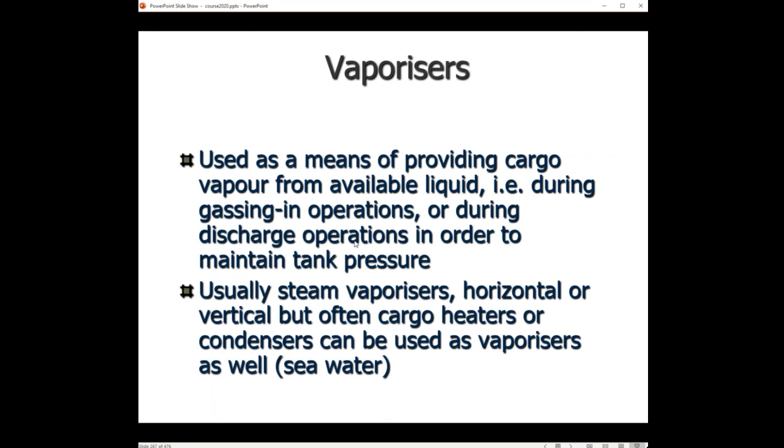When we discharge at a high rate, and the ambient natural evaporation of the cargo is insufficient to keep a positive pressure in the tank, then we will need a larger amount of vapors. We will start the vaporizer.